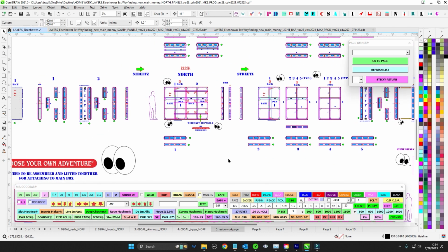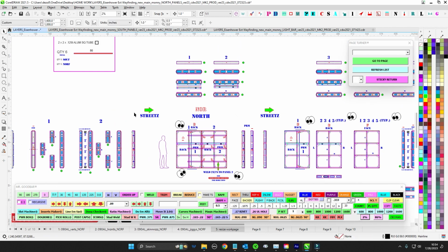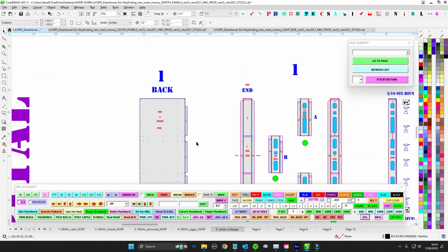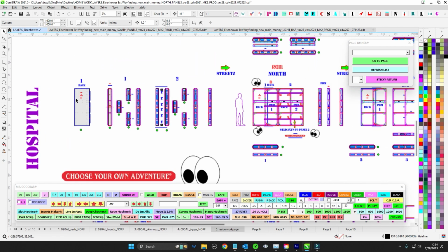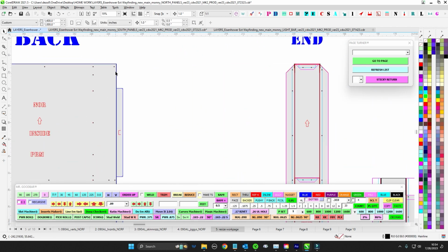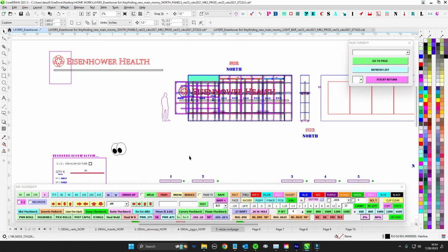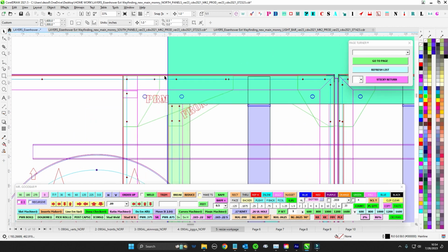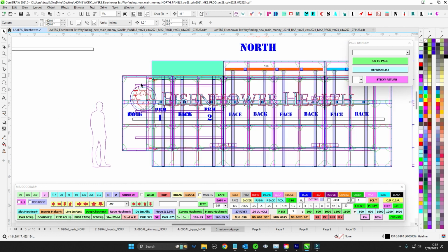Also, this is a note for install, 1 and 2 must be put on first, because what you're going to want to do is this skin, right? So all of these boxes do not have skin on the back side. They only have skin on the front side to save weight, plus it's not needed. But that means that when we skin the back side of 1, it's actually going to be poking out an 09. So when you bring this skin with box 1 onto the mains here, it's actually going to hook, because this 09 will be poking out the back a little bit, and then there's no skin on any of these boxes. So you're going to want to kind of start with 1 and 2.